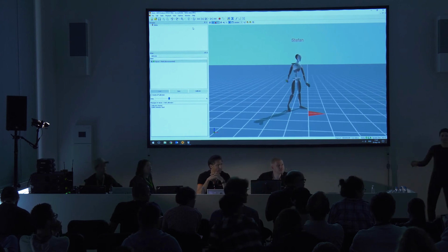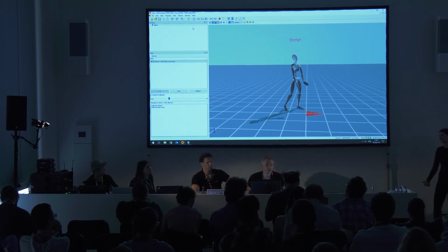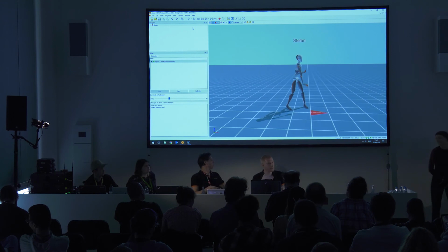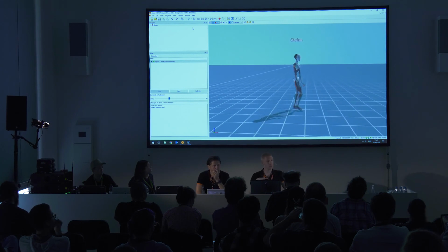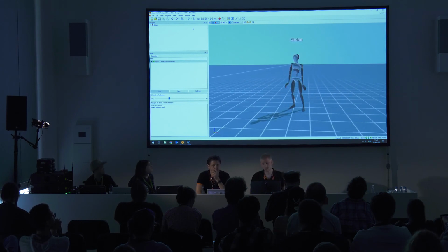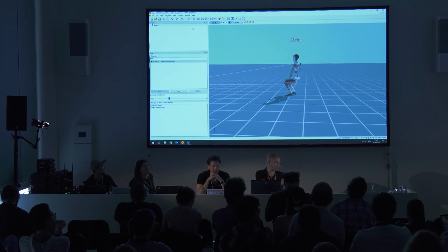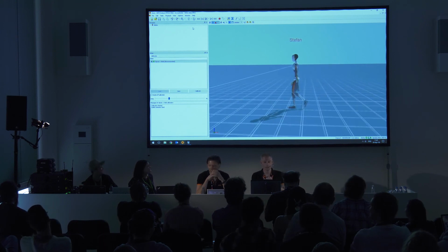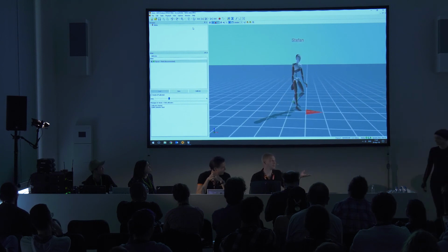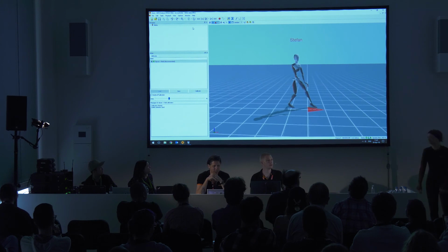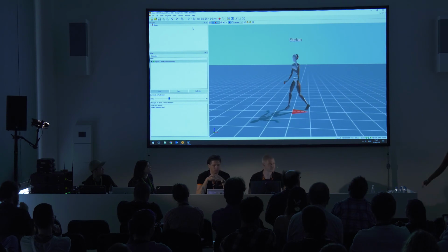One question, how stable is the world center position if you move around a bunch, like half an hour? Yeah. So what we have is what we call positional inaccuracy. So we calculate our position by looking at the biomechanical model and the rotations we get from the trackers. So we normally say that with a properly calibrated system, because it does have factors, of course, you need to properly calibrate it, and you need to do proper body measurements, you should be able to get up to about 1% drift. But do keep in mind that if she does stand still for half an hour, she will still be on that same spot. It really happens when she walks around.